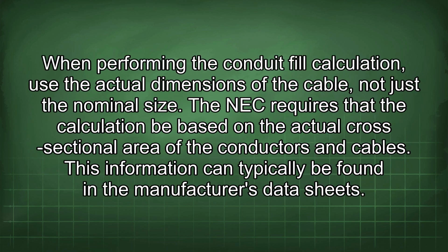When performing the conduit fill calculation, use the actual dimensions of the cable, not just the nominal size. The NEC requires that the calculation be based on the actual cross-sectional area of the conductors and cables. This information can typically be found in the manufacturer's data sheets.